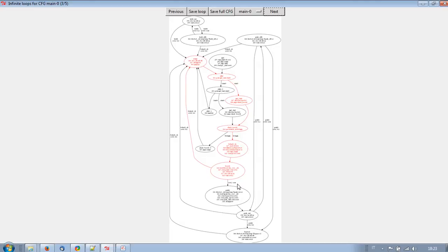This can be given by a faulty actuator or some other error condition for which the threshold current is never reached. So in this case, a timeout makes the program go back to the idle phase, deactivating its output.